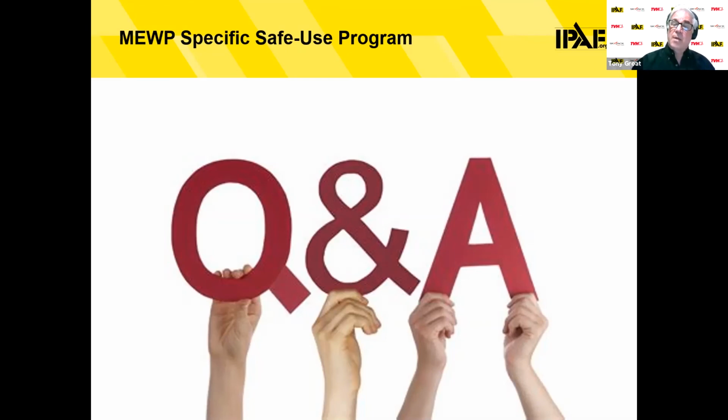So an example is if I'm in a position where I'm trying to do a task and I may be required to do what would be considered overreaching, there is a situation where a site risk assessment would require the use of personal fall protection on a scissor lift. But there is no specific requirement in the US to do that. To give you a corresponding view of that, in the Canadian standards, you are required to be wearing fall protection on all MEWPs when they're in motion. So that kind of gives you a different perspective.